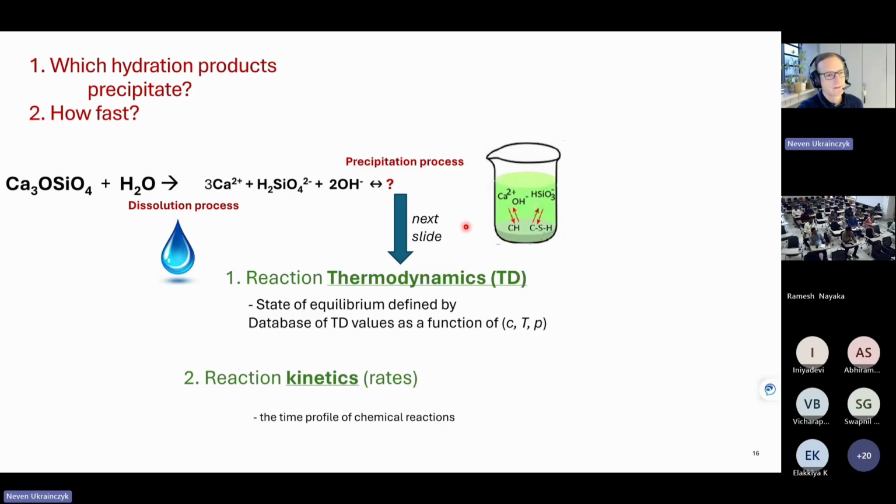And actually the cement hydration is metastable, and that's why we have the durability problems, because the final reaction is the calcium carbonate, or it forms some other expansive products that then destroy the concrete. And then the kinetics is actually the most important part that defines what kind of products you really have, even in terms of hundreds of years. The kinetics is still defining that you still have cement reacting, and you still have portlandite and CSH as metastable phases actually.